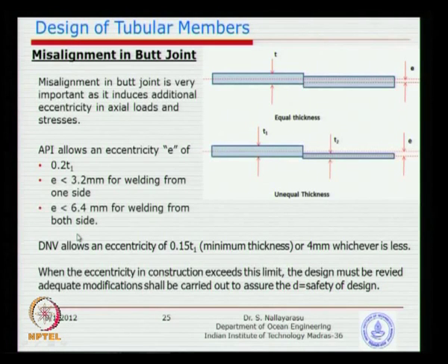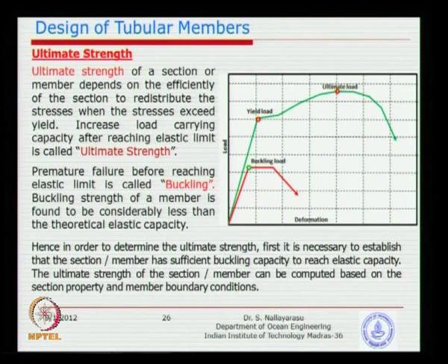If you weld from both sides, you have double, so that you can have the weld metal helping us. So, all that we are trying to conclude is that there are inherent built-up stresses even before it receives the actual design stresses. So, you allocate some portion for your residual stresses and the mistakes.